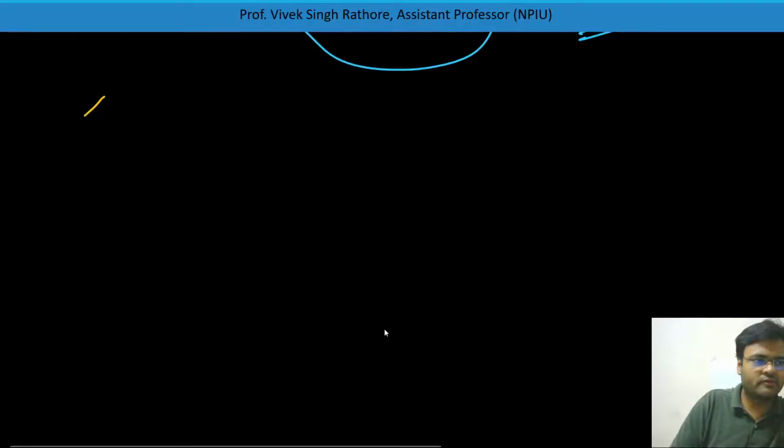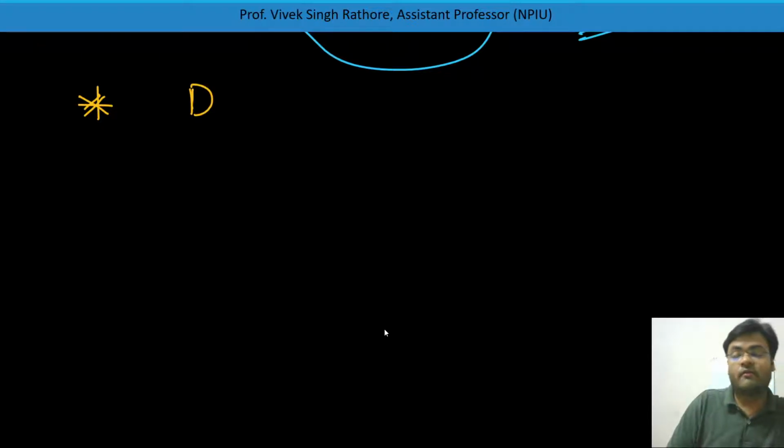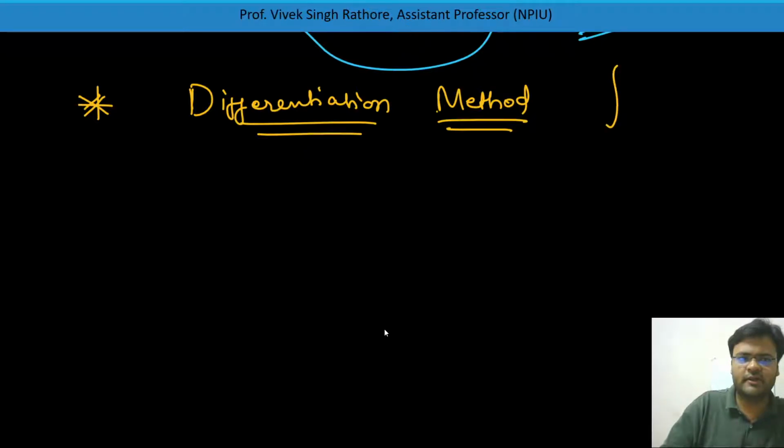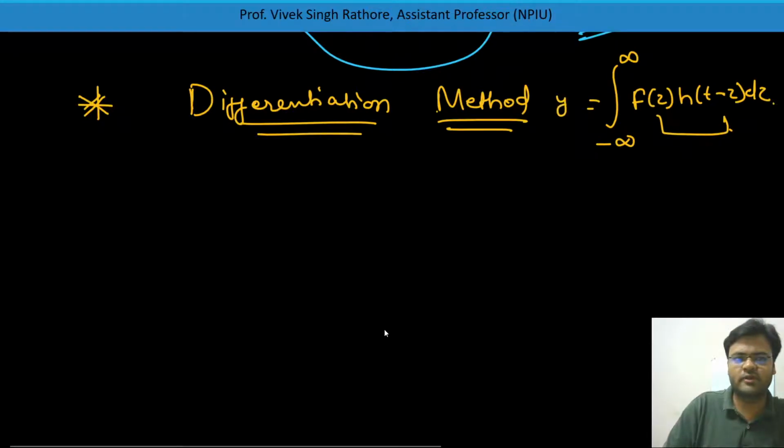So let's see, I will tell you another method of how to do convolution, using the differentiation method. We'll see our next method for getting the response of a continuous LTI system. Up till now, I have told you one method: integrate from minus infinity to infinity f(tau), h(t minus tau), d tau. If you can do the integration of this, then you can get your output as y of t. First method I told you like this.